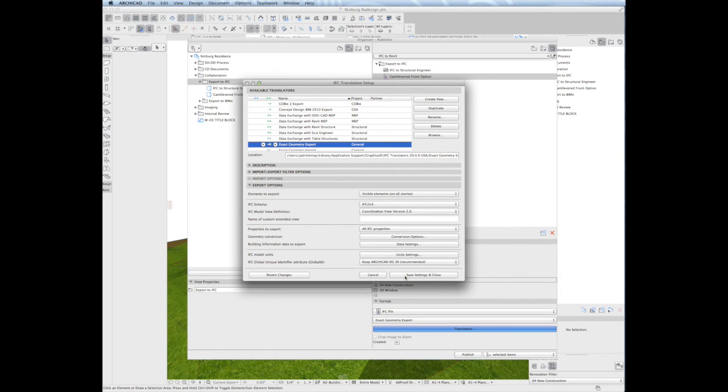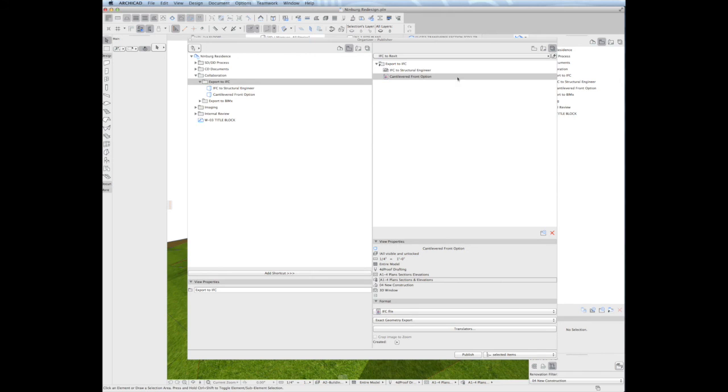read some of the modeling tools that ArchiCAD has, things like associated trimming bodies like solid element operators or the merge function, which don't always translate very well to Revit. Also, complex profiles don't always translate to Revit. So by using the BREP settings, you're going to get a more accurate appearance on your model. It's going to be represented properly.